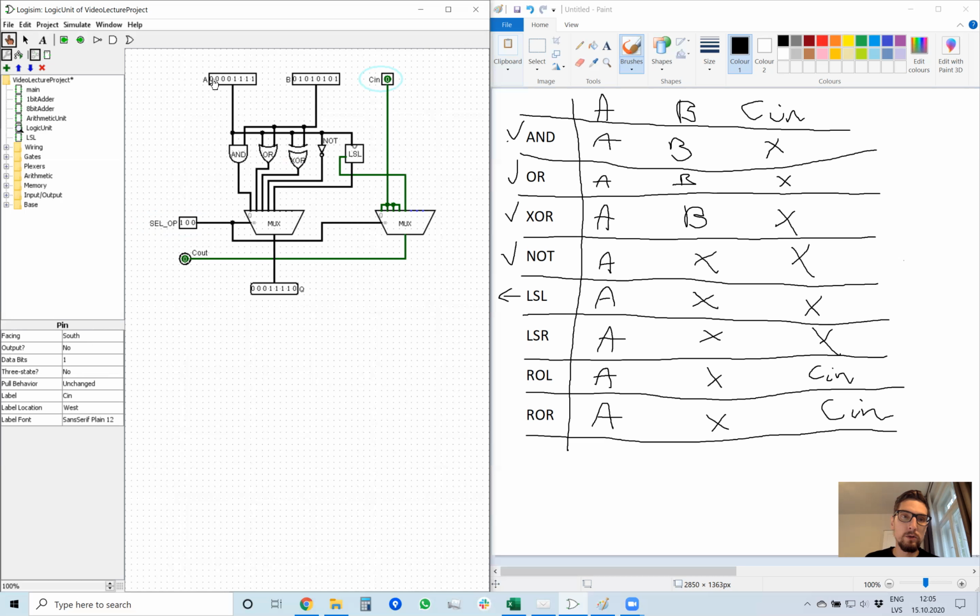So let's say I want to calculate, for example, logical shift left on this number 11001111. The output is 0 is pushed into the first position. Next bits are copied, 111101, and the last bit 1 is forwarded to carry out. Okay.